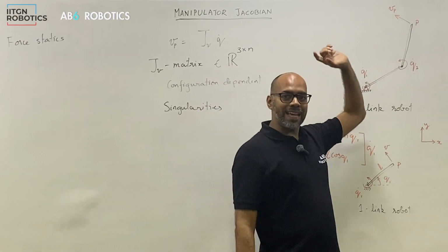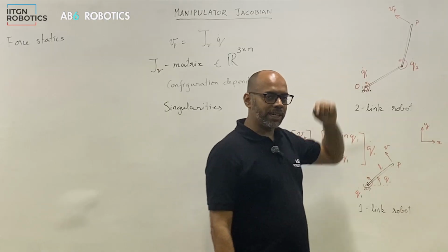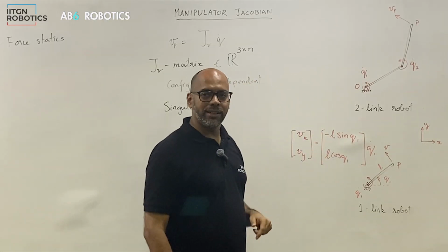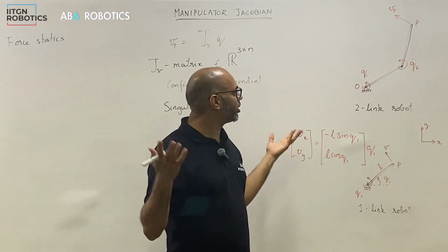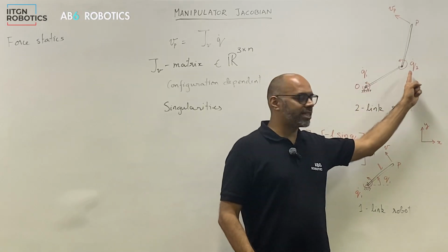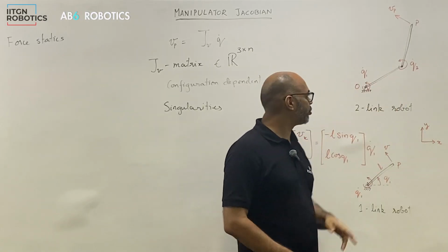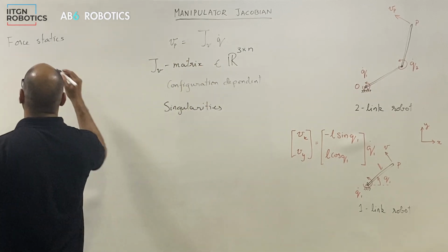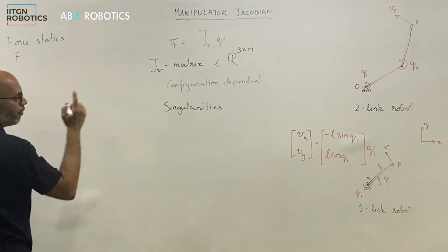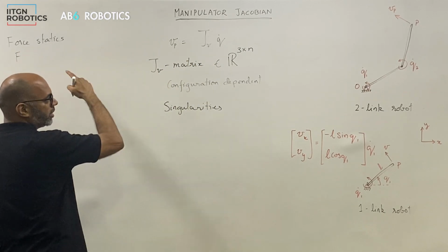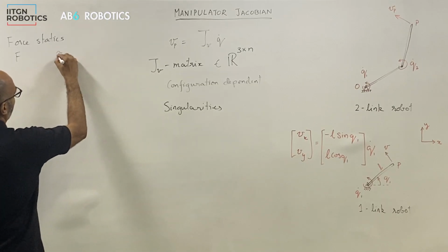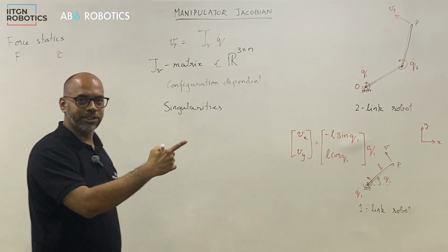Then the force F that the robot is applying on the wall, let's imagine that that's not directly measured, but you can measure the torques at the joint. So you have tau 1 and tau 2. So again, you would have a relationship between force applied by the robot on the external environment and the torques applied by the motor at the joints.